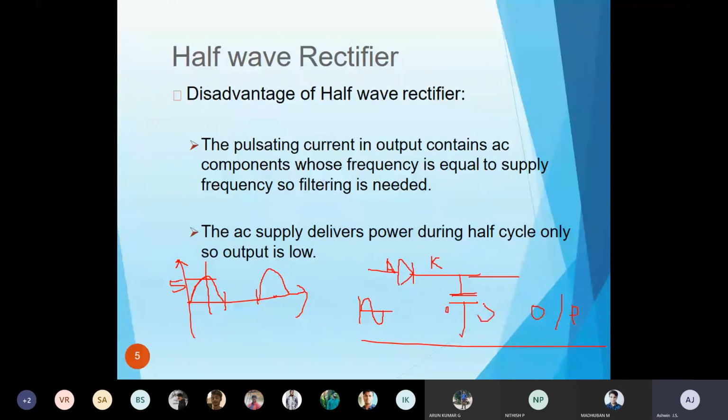Okay. Once here, what is happening after that? It is dropping to 4.9, 4.8 up to 4.0. So during this condition, the capacitor will discharge and it will deliver the additional voltage. So due to delivering the voltage from the capacitor, it will maintain the same value. So here I will draw the output. So once it is starting at maximum, after that, the capacitor will start to discharge. It will provide the stored value to your output so that it will maintain a constant, and slowly it will start to drop down. Why? Because it won't maintain the maximum 5 volt always. Surely there will be a drop.